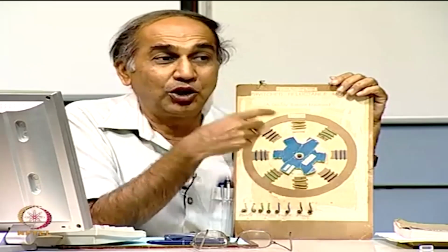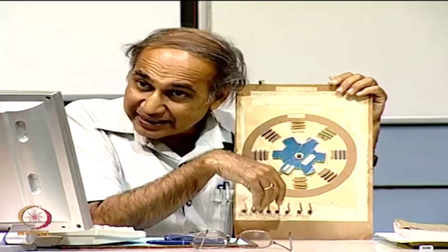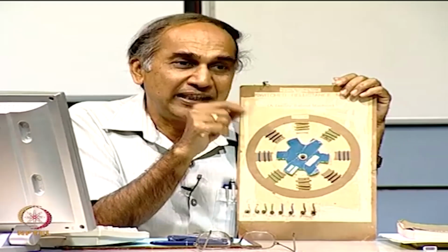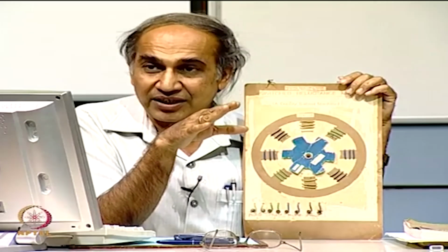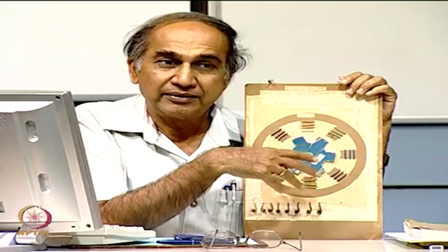So you know the mechanical torque by knowing the inductance profiles, and the torque will be I1 square dL1 by d theta plus I2 square dL2 by d theta, because it is a partial derivative with reference to theta keeping the current constant, and this is called co-energy. When you studied modeling, this is what it is, right.